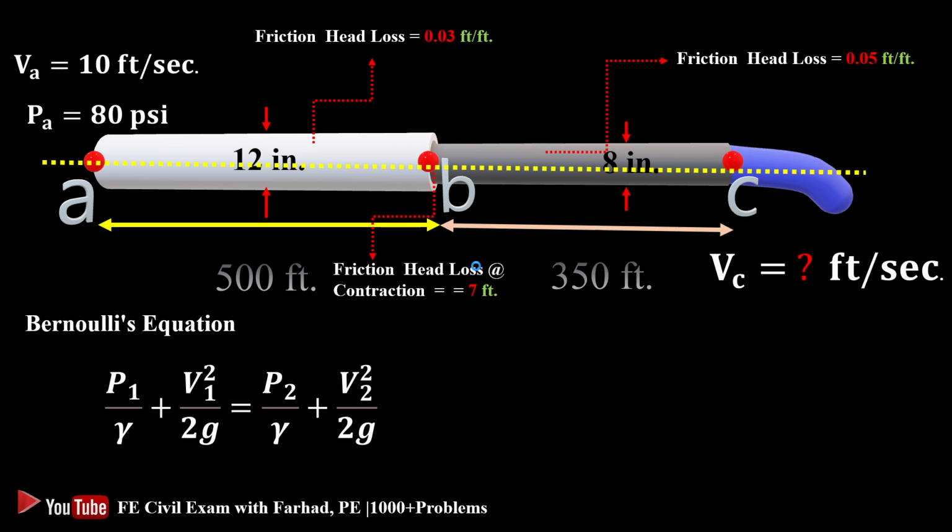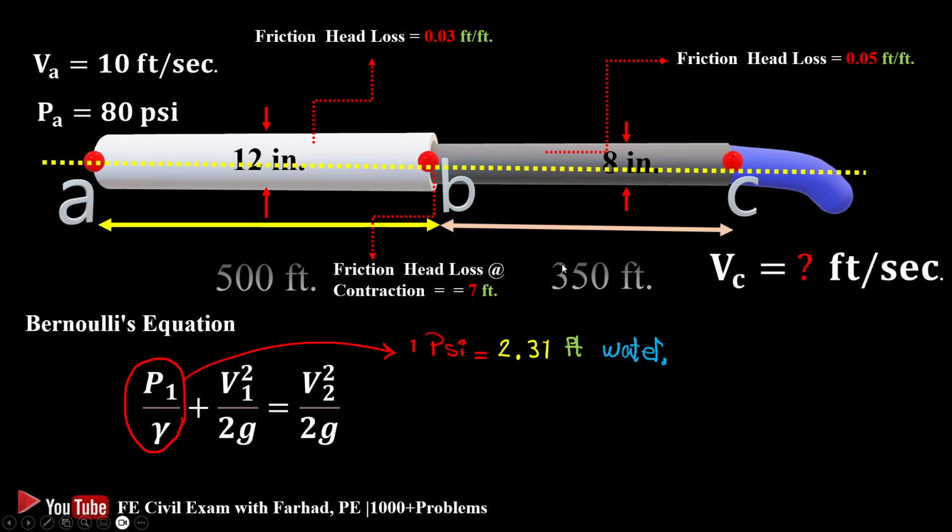So our Bernoulli's equation simplifies to this version, excluding the elevation. And also we do know that at the exit point we have a free jet. At a free jet, pressure is 0, so this term P2 over gamma goes to 0. So again, we can simplify the Bernoulli equation.